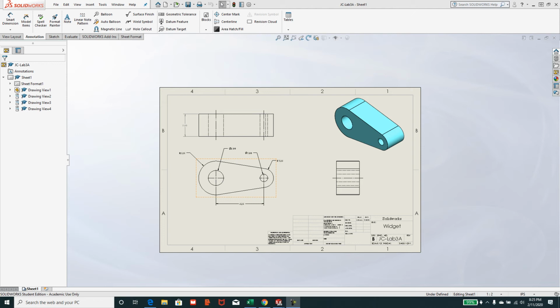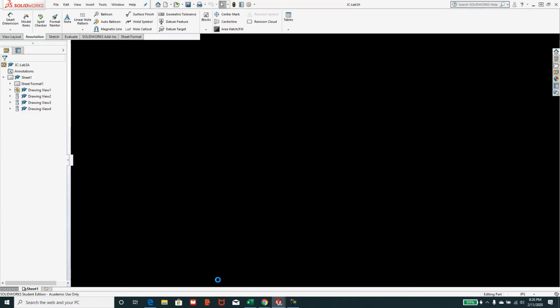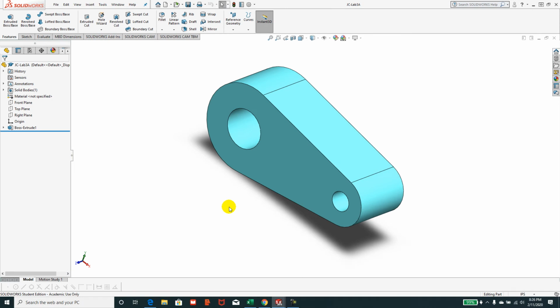Okay, exercise 4-1 continued. Joe Cerrone, this is SolidWorks, and we're going to create this part drawing from the part that we previously modeled. In the previous session, we created this part, and after we've saved that file, we go through and select New, Make Drawing from Part/Assembly.